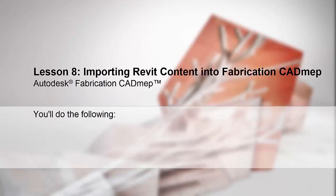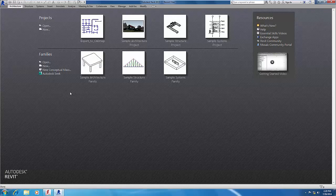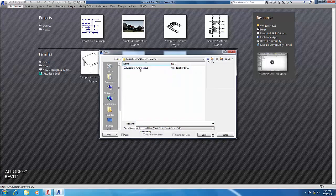For this lesson, you'll do the following. Export design line and graphic elements from Revit. Import into CADmep. The first method uses the Store Design Line Elements command. Start Autodesk Revit or Autodesk Revit MEP and select Open. Browse to the exercise folder and open Export to CADmep.rvt.